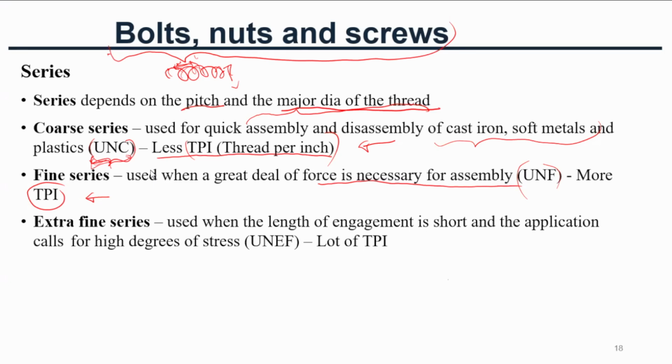In this case it has very fine threads, so a lot of threads per inch. This extra fine series is used when engagement length is short but the load or stress is high.